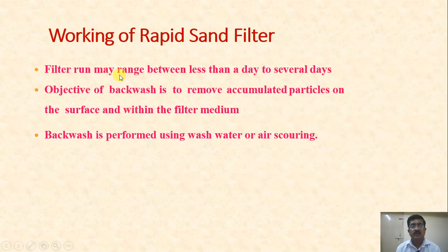Filter run may range between less than a day to several days. The objective of backwash is to remove accumulated particles on the surface and within the filter medium. Backwash is performed using wash water and air scouring, as we have seen.